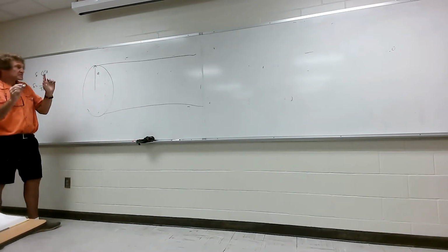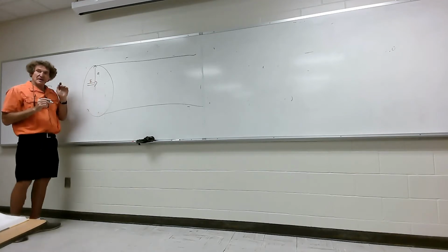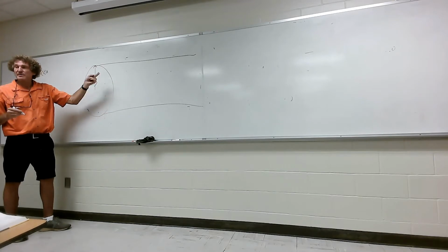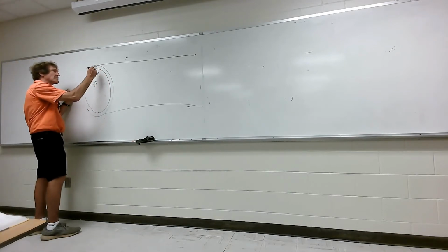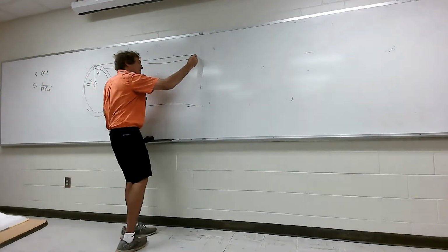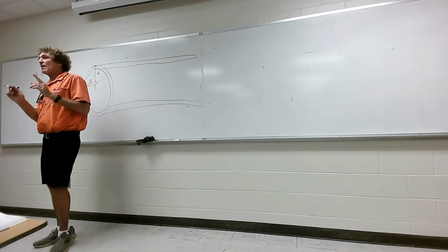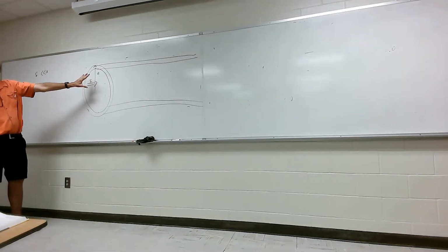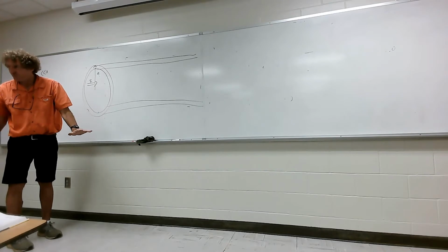Now this gets a little weird. I know I have current flowing this way, but really it's not going to go down the center of the wire. It's not uniformly distributed. All the current is going to be contained within one skin depth of the outer cylinder. Now, when power's flowing, there's an electromagnetic wave. Remember, this is usually part of a two-conductor system where you have another wire down here carrying the return current. Follow me?